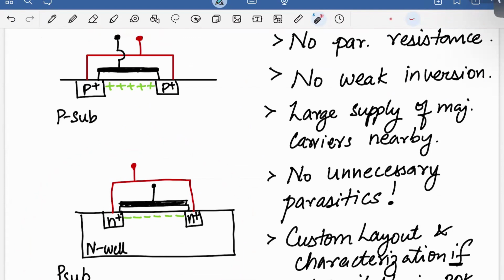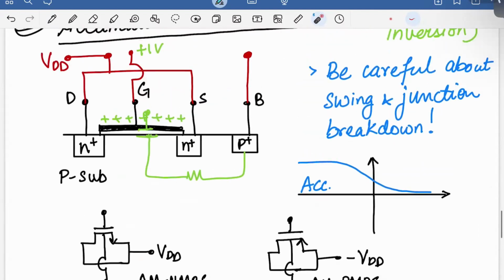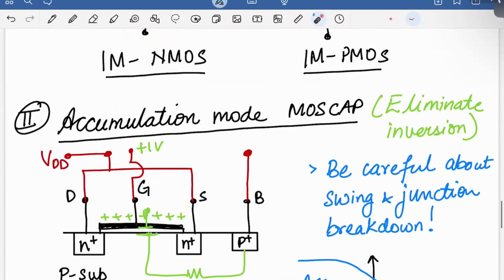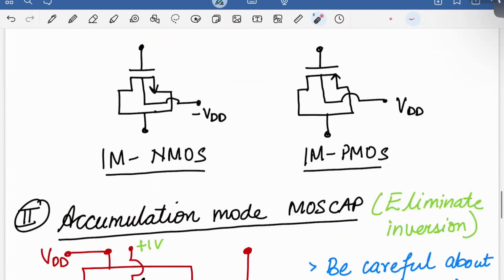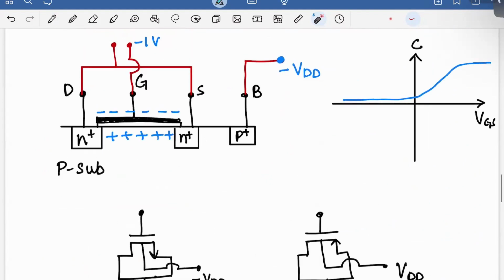You have to look at RF MOS varactors, and you'll see that they are usually PMOS varactors, although you also have the option of NMOS. But yeah, okay, let's go into Cadence now, and we'll take a regular transistor, connect it up in different ways and see what the capacitance, what the Q, and what the CV characteristics look like.